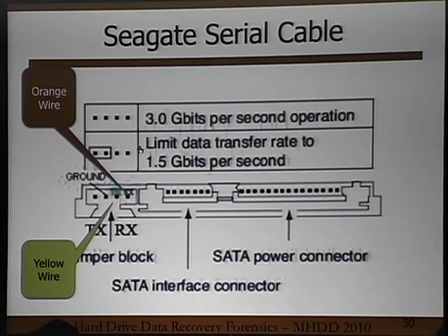Now, on the back, all Seagate drives have a serial port that works just like a modem. You hook up these 2 wires, you start up a terminal, and you talk to the drive through a serial port. I don't mean the SATA interface, I mean there is a serial port. I mean like a Courier modem blinks at you, you unplug the cable, you plug it in, that's what I mean, literally. So I'll show you that in a second.